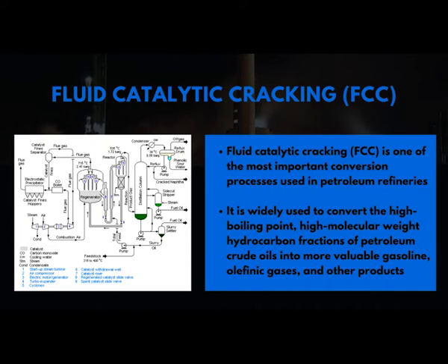Then the next unit is known as the fluid catalytic cracking unit, or in short FCC or FCCU. Here the residue is heated and then undergoes chemical reactions in the presence of a catalyst. The catalyst consists of fine solid particles, which are in a fluidized state.